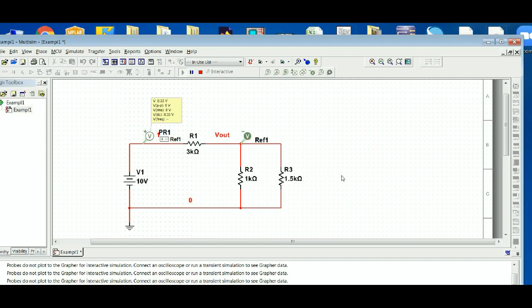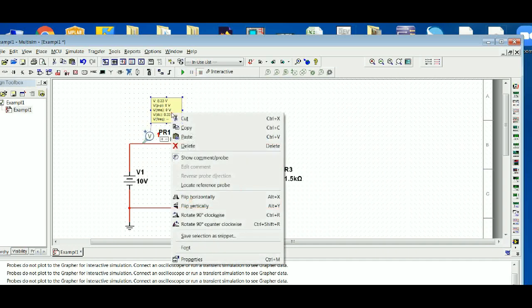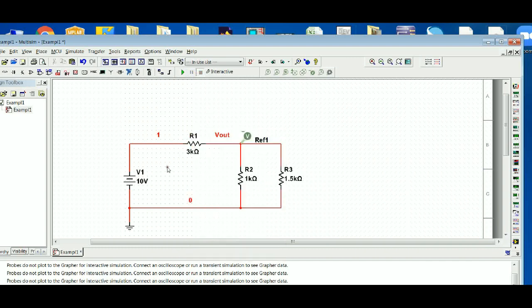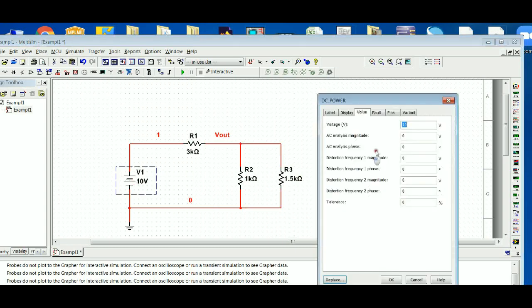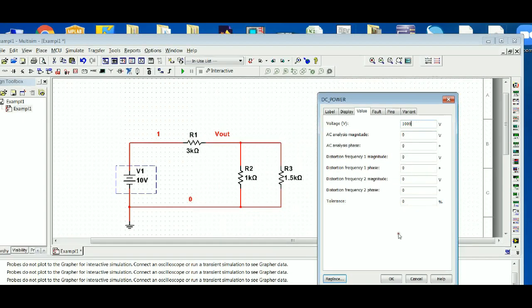So we've talked about three probes here, voltage, current, and differential probes, and I think it should impress you as being pretty cool for simulating circuitry. I'm going to delete this, and this too. Now to show the nice part about using the virtual simulation, I'm going to do some damage in the circuit, and I'm not going to pay a whole lot of attention to when I'm going to overload the resistor, and remember each one is rated for a 1/4 watt. So I'm just going to set this voltage to 1000 volts, and for sure that's got to do some damage.